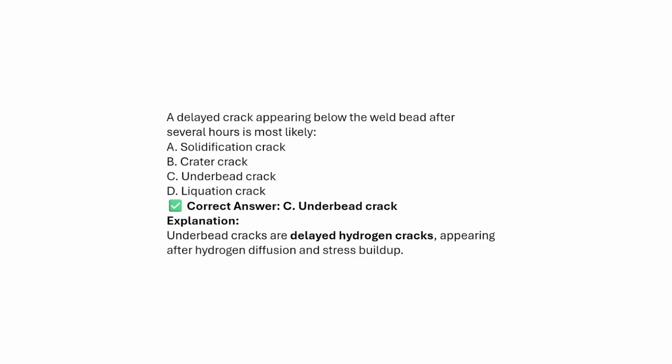So solidification cracking, no. Crater cracking, that is also no. Solidification cracking is at the center of the weld bead, crater cracking at the end of the weld bead. Underbead cracking, yes, that could be. And liquation cracking happens at the HAZ. So the answer is underbead cracking, the delayed hydrogen cracking appearing after the hydrogen diffuses and stress builds up.